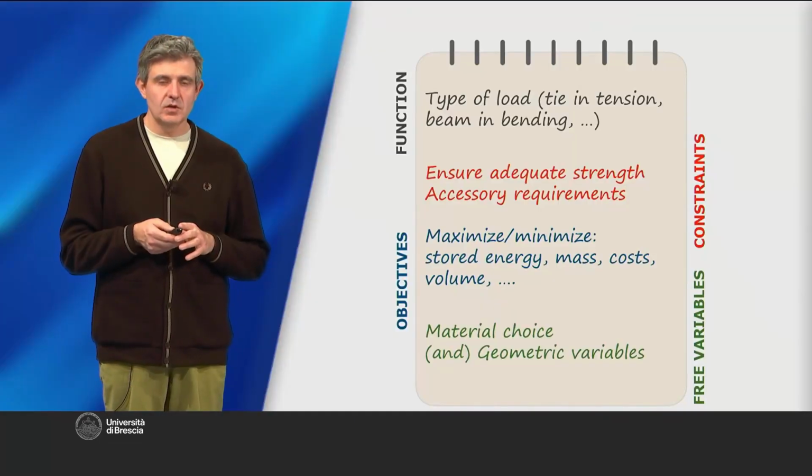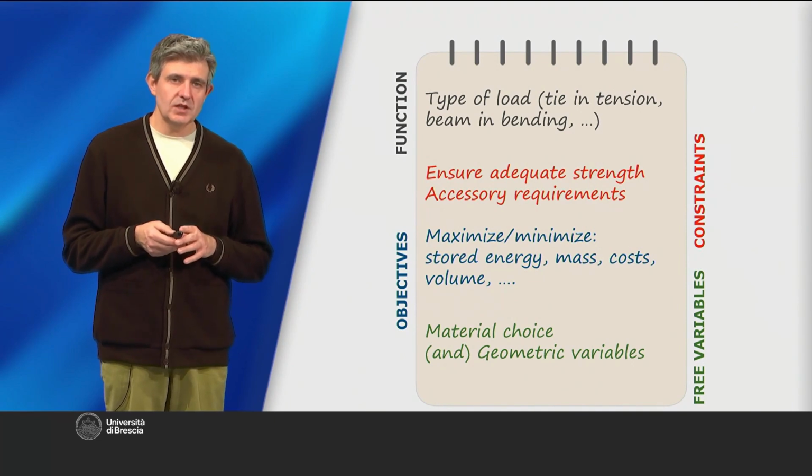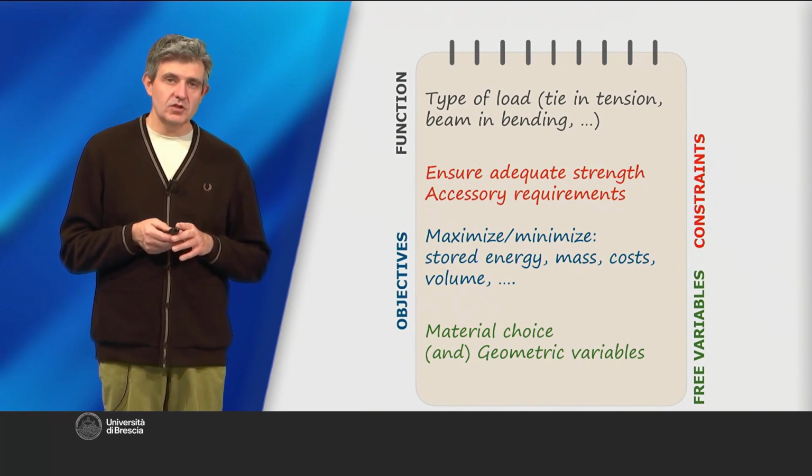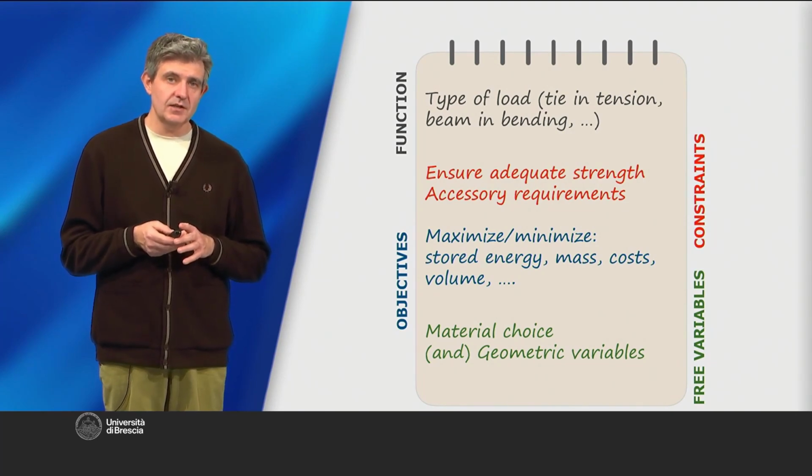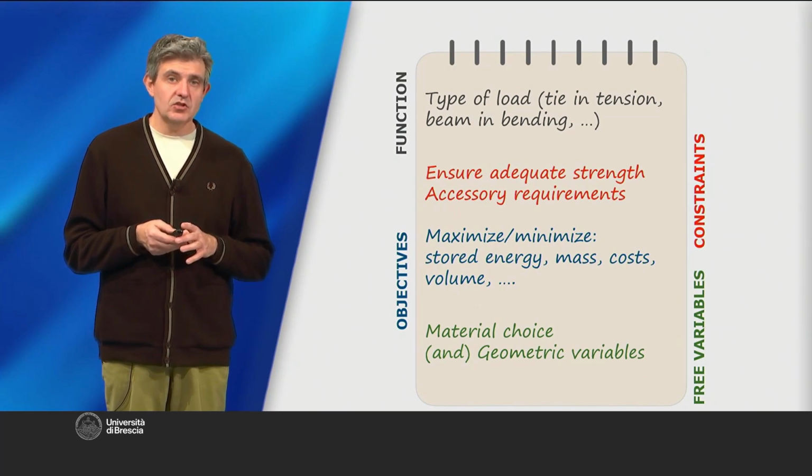In a design driven by strength, the approach to material selection still starts with translating the project requirements. Generally, when translating the project, the items will be organized like this. Under the function heading, you'll specify the type of product you're designing. The constraints will mainly concern strength, particularly failure, and the type of strength the product must withstand. Afterwards, any secondary constraints will be specified. The objectives will show the parameters that should be maximized, like the energy absorbed, or be minimized, like mass, volume, or the overall dimensions.